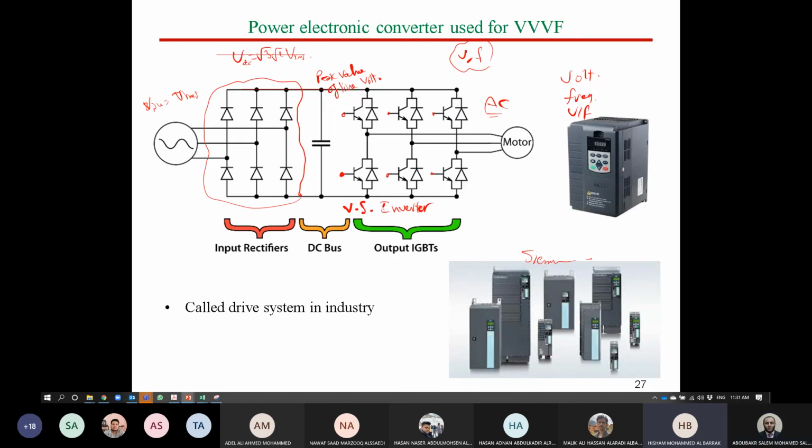Actually, in this case, usually in the drive itself, we don't have a capacitor to overcome the harmonics. Am I right? We don't have capacitors? Yes, because as you said, Doctor, the output AC will carry some harmonics because of the switches. This is the normal operation for voltage source inverters. You will have some harmonics. What is the relation with the capacitor?